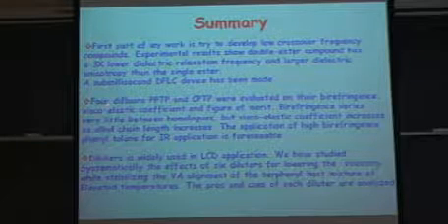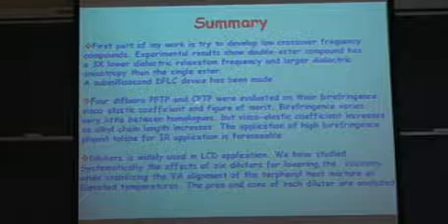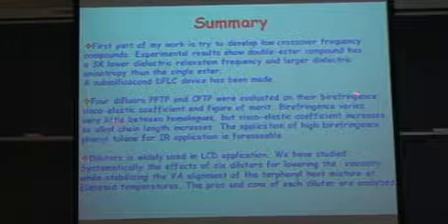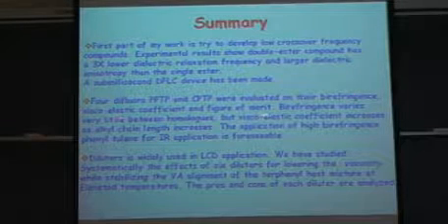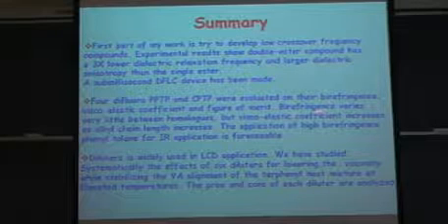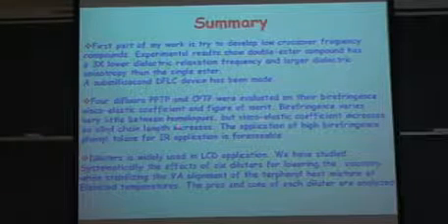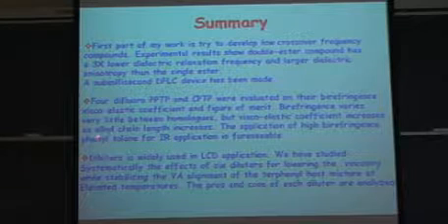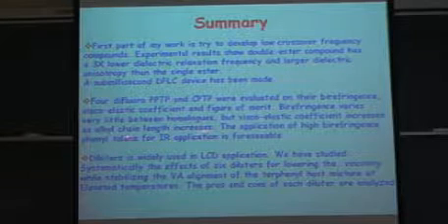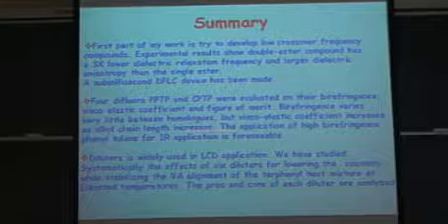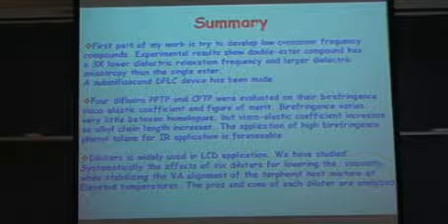Secondly, difluorophenyl and cyclohexyl compounds were evaluated on their birefringence, viscoelastic coefficient, and figure of merit. Birefringence varies very little between homologs, but the viscoelastic coefficient increases as alkyl chain size increases. The application of a high birefringence phenyl compound for infrared application is foreseeable.